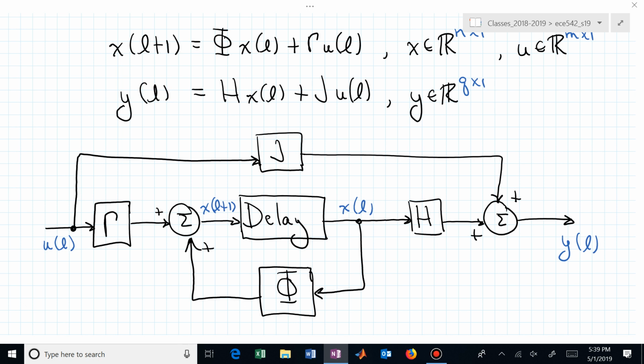You can easily, well, I maybe shouldn't say easily, but you can extend a lot of these ideas and concepts to multi-input, multi-output systems much more easily than if you start in a transfer function domain or setting and say, okay, now I have 3 inputs and 4 outputs. I don't know what I do. Here, you just build the gamma and the H matrix to incorporate those multiple inputs and multiple outputs.